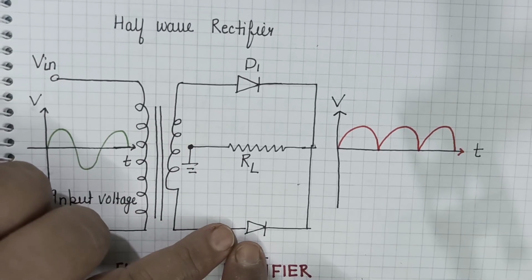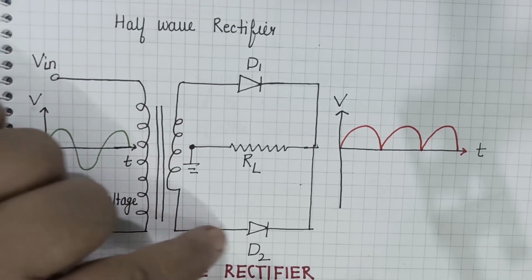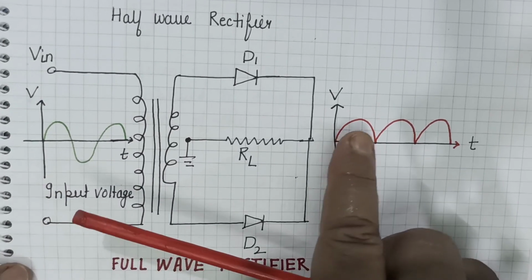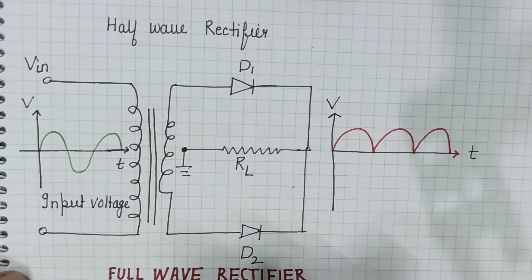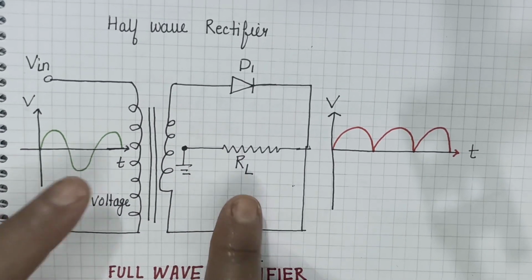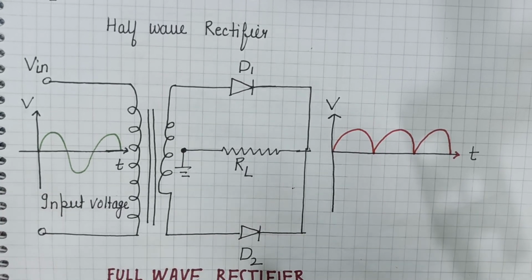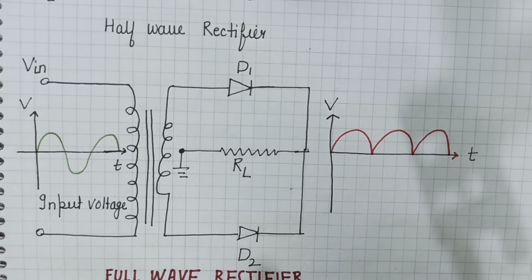So this time D2 is forward biased and D1 is reverse biased. So D2 will conduct but in the same direction through the load resistance. So output will come as fluctuating DC. Learn to draw this diagram, draw it twice or thrice. So this is a quick revision of at least the most important and expected questions I have discussed in these 15-16 minutes.